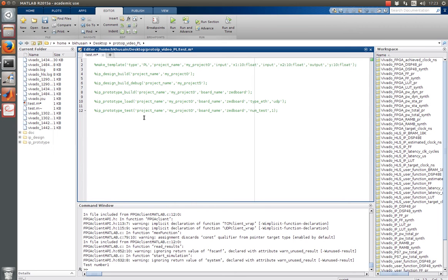In debug mode, we can actually open the underlying project. By project I mean the Vivado project, Vivado HLS, Xilinx SDK project, in order to manually make changes. So once we learn new things about FPGAs, if we want to take control over some low-level implementation details, we can call the corresponding debug command and change the project settings manually.